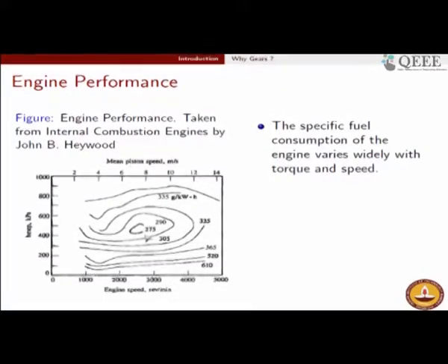So if the engine has to operate economically, it is imperative that some other device is envisaged such that the engine keeps running at this amount of torque and this amount of speed, but something else, which is precisely the gear, will supply the diverse amount of torque and the diverse amount of speed associated with the different operating conditions. This is exactly what is done by a gear.